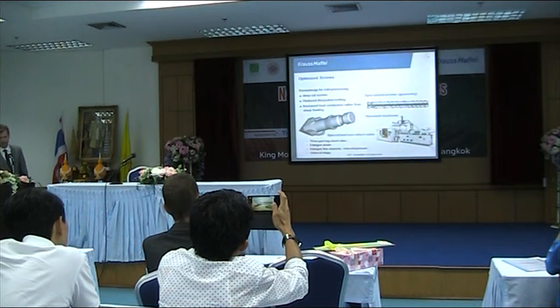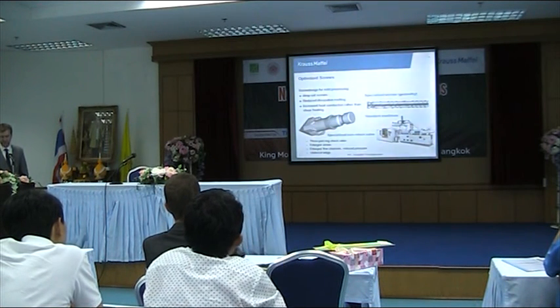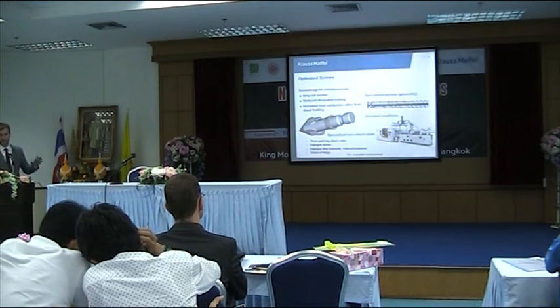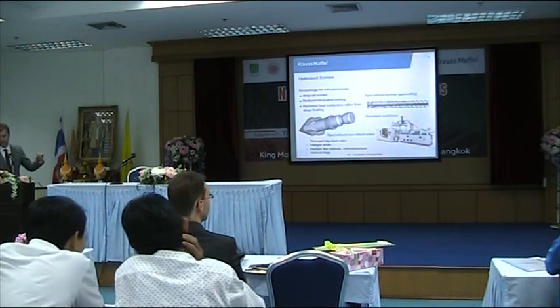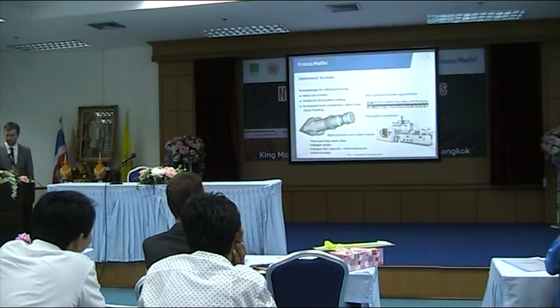Of course, if you would like to treat natural fibers, you have to use some specialized screws, for example, on the right side, deep cut screws for reduced dissipative melting. So you will have increased heat conduction by the heating elements outside of the barrel, and rather no shear heating, because it may destroy the fibers.